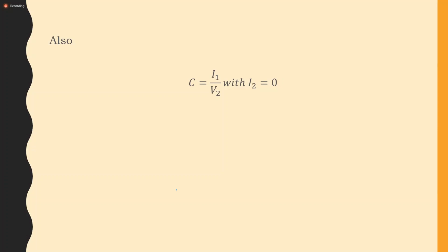Would it be 5 over 30 minus I1? No, sir, no minus. We're dealing with I1. All I'm looking at is I1 flowing in. 5 over 30 times I1? It's 35, yes. So it's 5 I1 over 35. So that's the current through the 20 ohm. Does everybody agree with that?